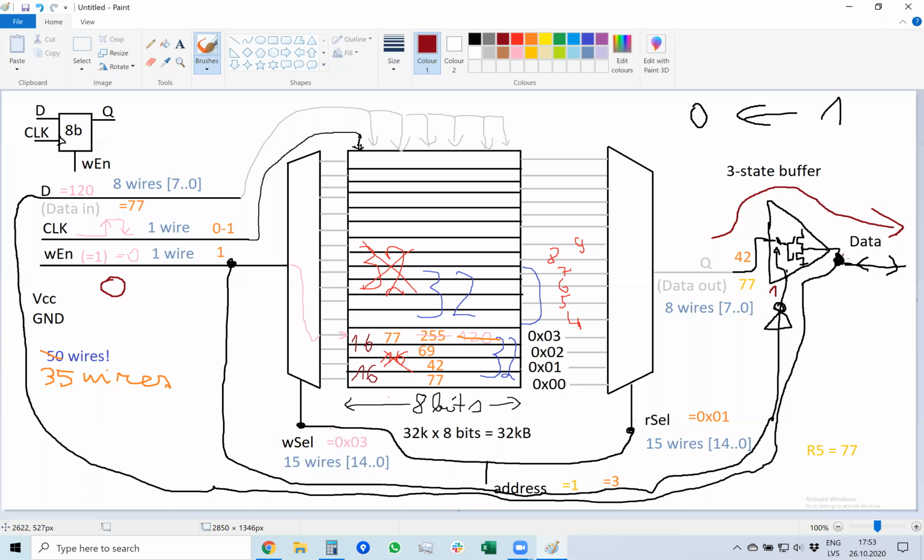However, if we set write enable to 1, then this output enable is 0. This thing is switched off, doesn't output anything, and then data comes from the microcontroller into these data lines into the memory and is written into the memory. And this is called three-state buffer. And actually, all microcontroller pins are three-state, because if you take, for example, an Arduino microcontroller or any other microcontroller, you can tell its pins to either be input or output.